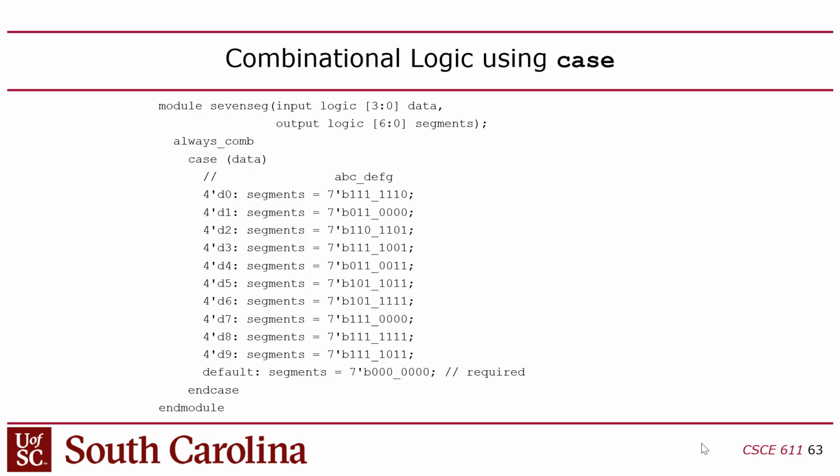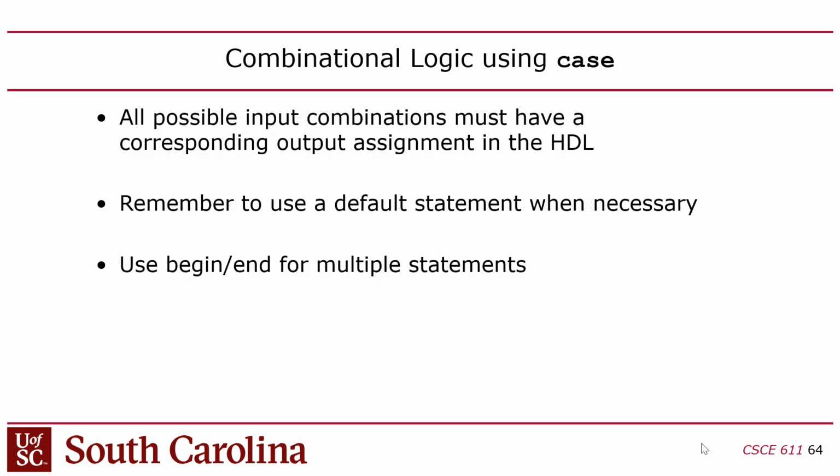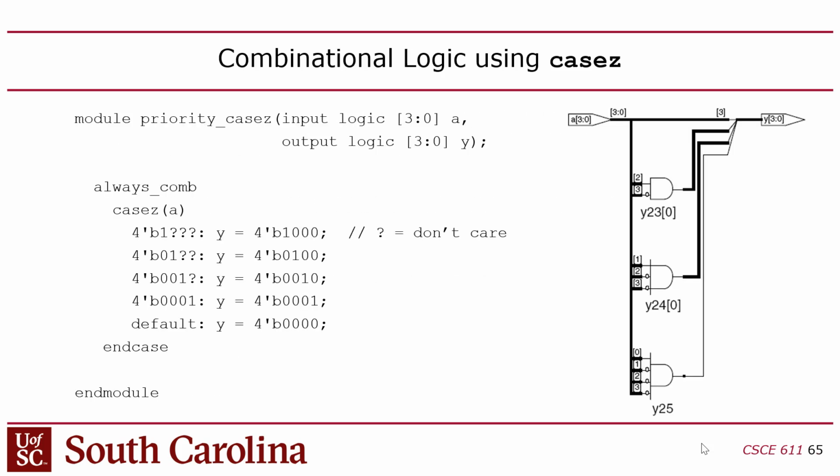And in this case, I'm now using a case statement. So in addition to if statements, you can use case, although you'll notice the syntax is a little different than what you might be used to. And each one of these cases can also have begin and end if you want them to be multi-line. Make sense? But this is essentially equivalent to a switch statement in C or in Java. There's a variation too called casez where you can include don't cares in there as well.